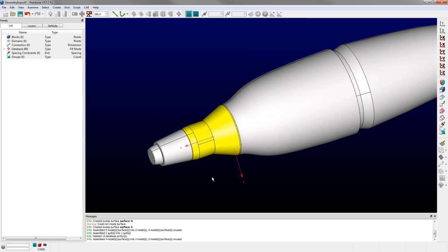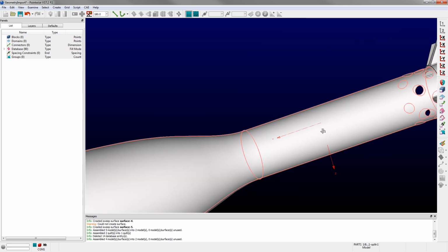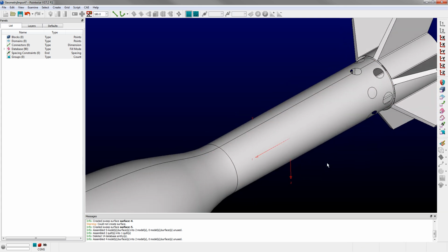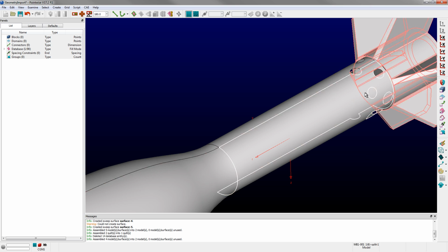All right. Now I'm going to do the exact same thing for these holes on the back. Okay. So I'll walk through this process again so it's clear. In this case, there's one. You'll notice this hole up here. That's part of the boundary of the quilt, which means that I can't just use this quilt and untrim it. If I untrim this quilt, it's only going to allow me to select the holes that are on the interior, not that hole on the boundary, okay, because it's a part of that boundary definition.